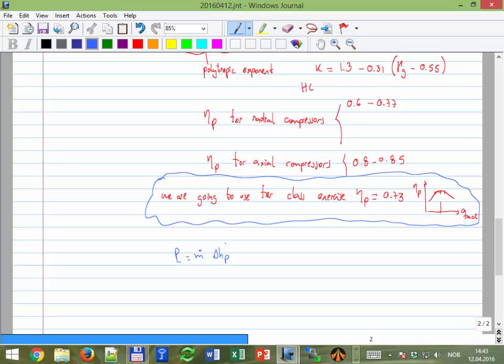We have an expression for that, and the mass flow we can calculate however we want. We can use the standard conditions rate times the density at standard conditions, or the actual conditions rate times the density at actual conditions. We have many ways to calculate the mass flow. And what else do we need? Temperature, power. What else did we mention last class?